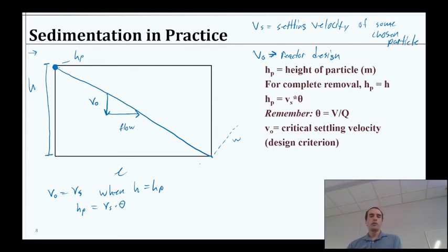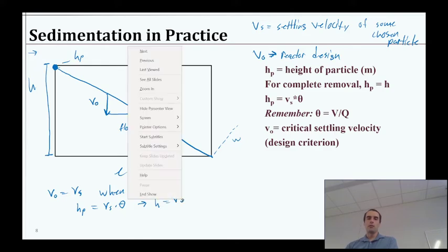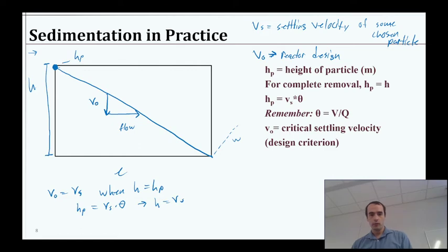And so here, since we're saying H is equal to HP, to design the reactor, we're going to say H is equal to that Vs. And now we can write it as V naught, because we're doing the reactor design, times theta. Okay? So in this instance, theta is time? Theta is time because remember that theta is hydraulic retention time. So theta is the term that our book uses for hydraulic detention time. And thank you, that's a great clarification.